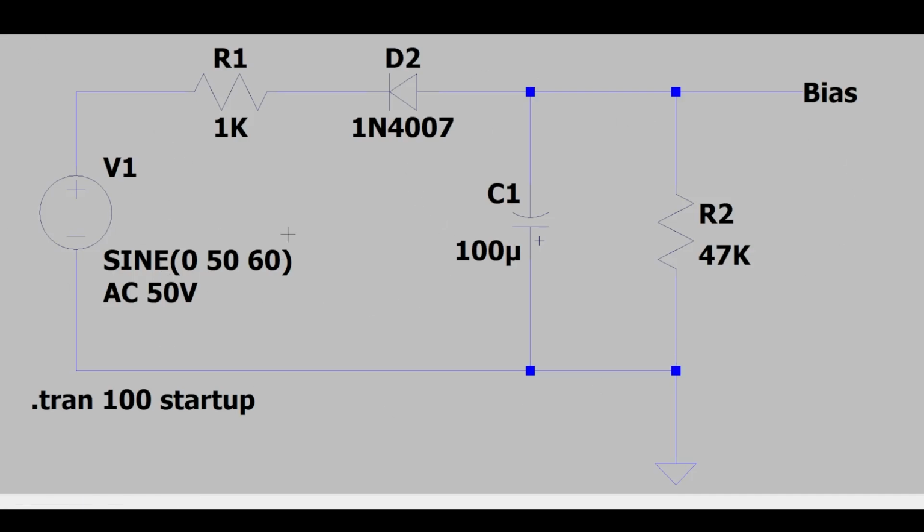Now, it could be in your Hiwatt you don't feel like you need to do this. You're okay with having a fixed, non-adjustable bias. I would argue that most of us could benefit at the very least from a modification that allows for a variable bias, changing out this resistor with a fixed limiting resistance, as well as a trim pot that can allow this value in DC to be adjusted for modern tubes.